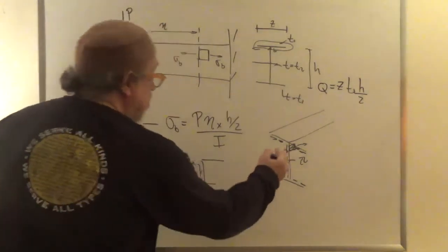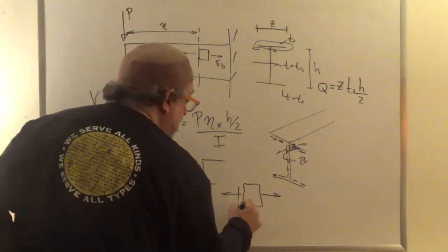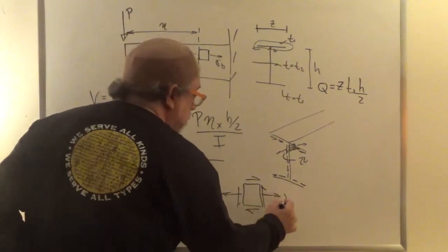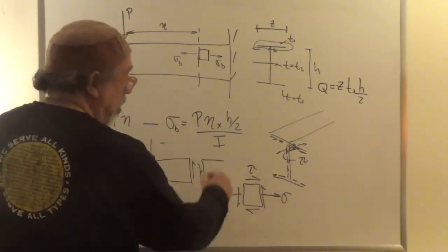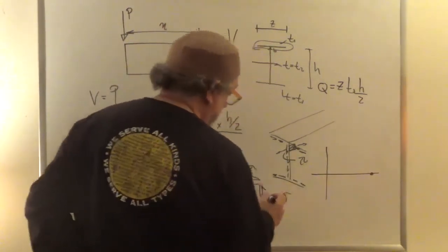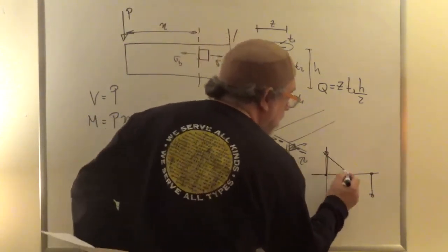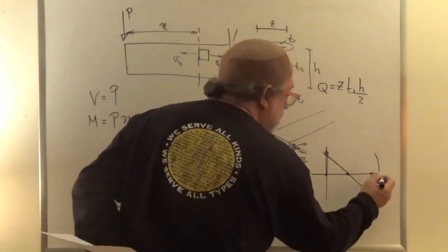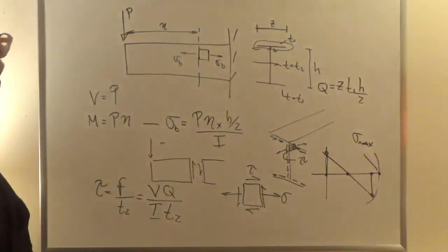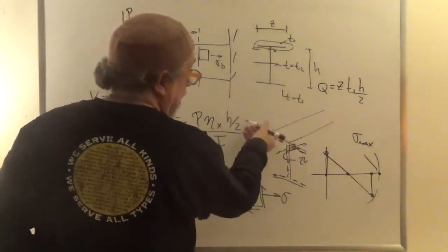Then once I know the shear stress and the sigma, I have a Mohr circle problem with sigma, shear, shear, right? We know sigma, we know tau. That problem is a Mohr circle problem. To find the maximum tension, I go with my sigma and my negative tau, and I go with my 0 sigma, my positive tau. So like this, find the radius, make the circle, this is the maximum tension, right? And that's what we have to compare to the allowable. That tension is not in this direction, it is in an inclined direction, right? At that point.